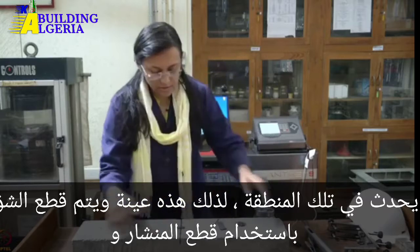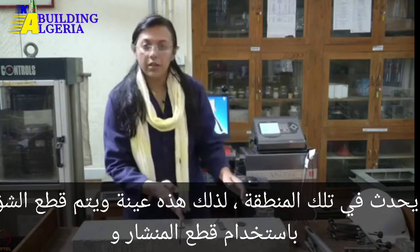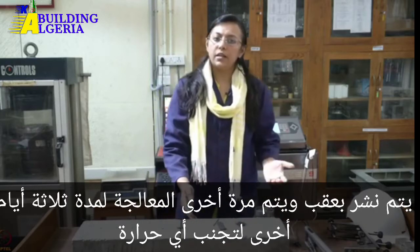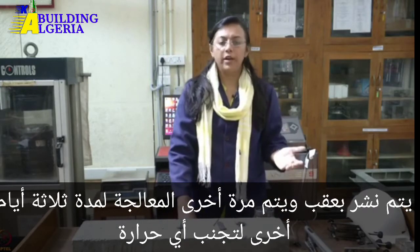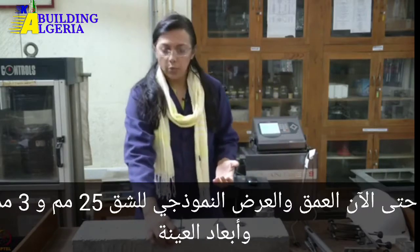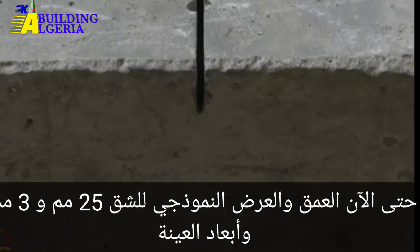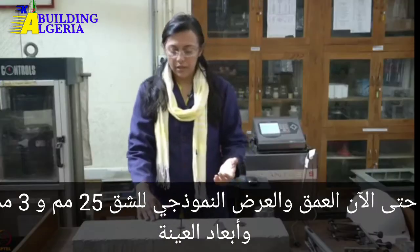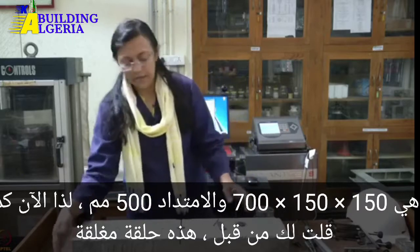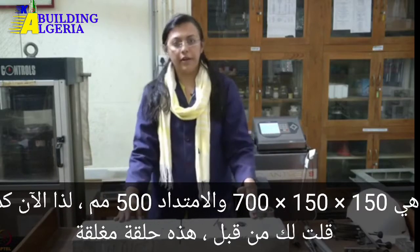So this is the specimen, and the notch is cut using a saw cutter, and wet sawing is done, and again curing is done for another 3 days to avoid any thermal cracks. The typical depth and width of a notch is 25 mm and 3 mm, and the specimen dimensions are 150 by 150 by 700 mm, and the span is 500 mm.